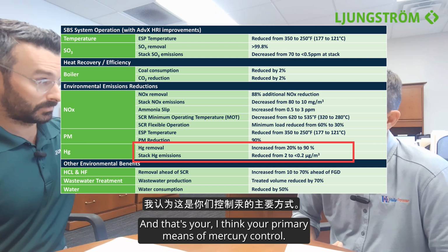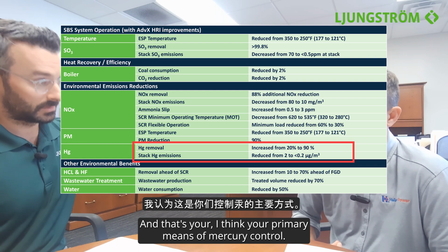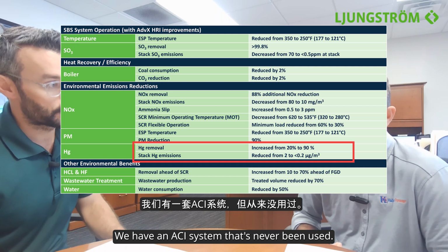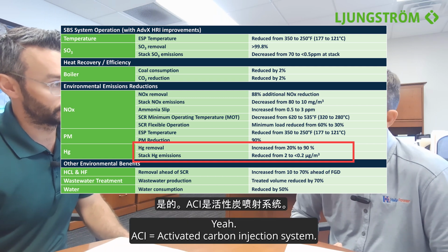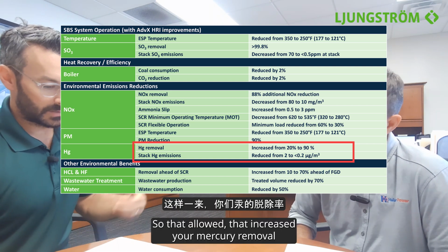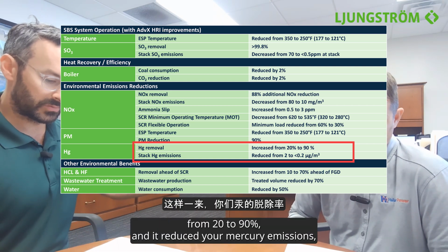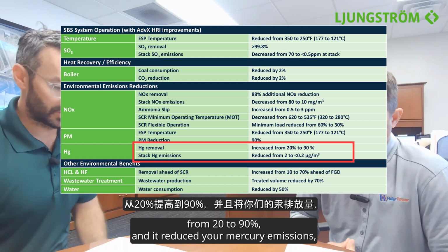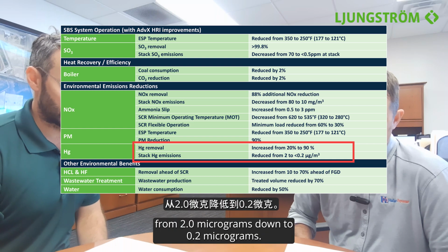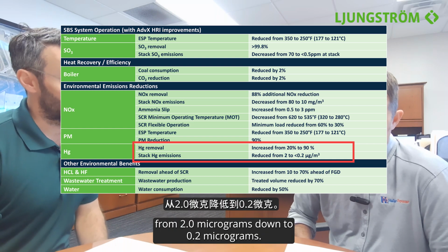And that's your primary gains of mercury control. We have an ACI system that's never been used, so activated carbon injection system. So that increased your mercury removal from 20 to 90%, and it reduced your mercury emissions from 2 micrograms down to 0.2 micrograms.